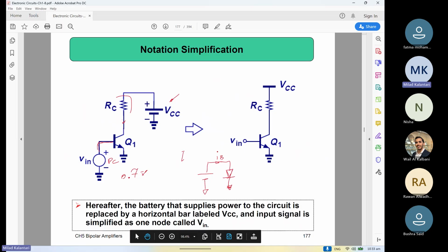It's not very well defined, right? It's because the diode current is basically an exponential relation, so it can easily get very extensively higher. It's not very well controlled. If you change the VBE, the current may change exponentially, too fast, right? So you do not have that much well control over the IB and again IC, because IC also is beta times IB, right? So this is not a good scheme, right?